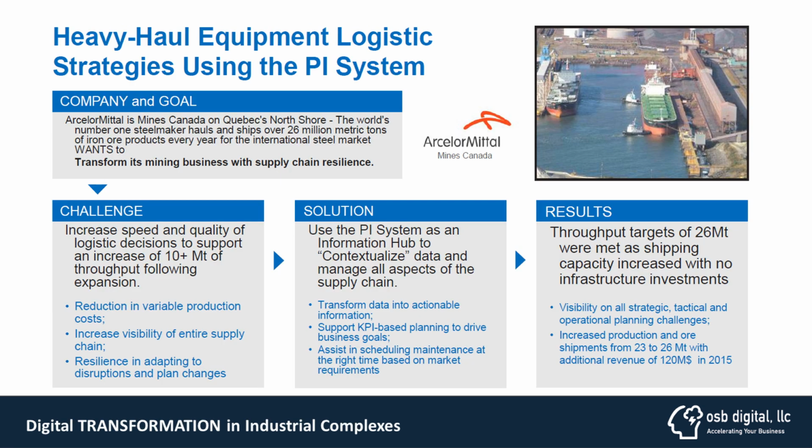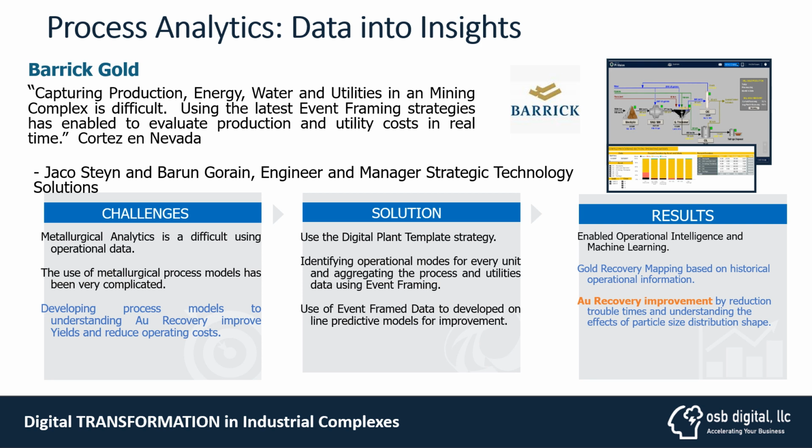These are some of the applications that we have been able to do using this concept, this one at ArcelorMittal, where they are making a lot of money. In this case, it was not flotation, but gravity separation that is used here. The particle size plays a big role there, as do the viscosity and the densities of the material. Here we went back into the milling, into the mine, and to the blasting. So it was a tremendous project that we did there. This one is at Barrick Gold, where we did more optimization and increased the gold recovery.